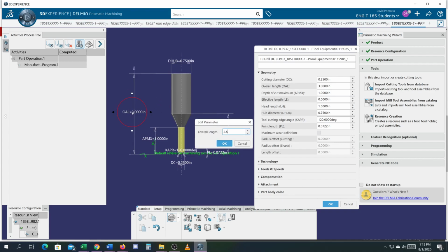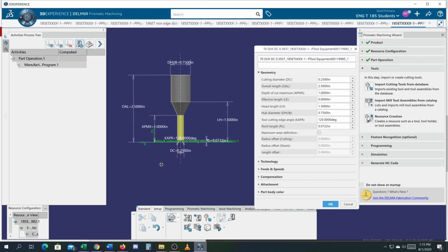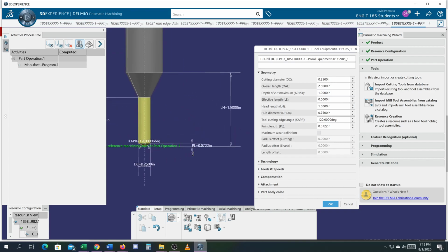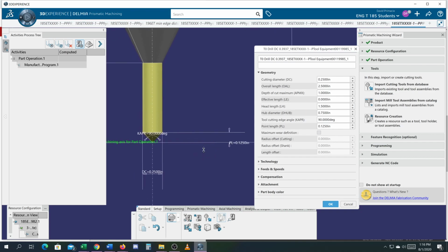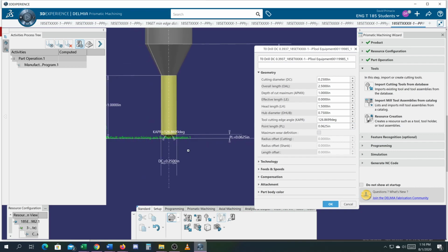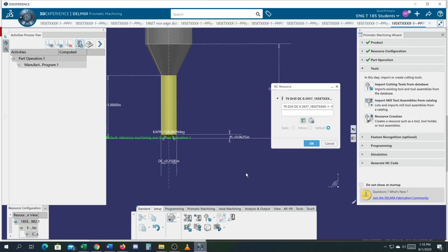Like this, 2.5 inches tall. Alright, so you can edit the values to whatever you need. There's standard heights and all that, but for clarity, I'm just going to put these in like so. Let's go 16th, so I'll do 1/16 and hit tab. Okay. So I've got all my geometry defined for the cutter. Most companies you work with, that's already going to be defined.